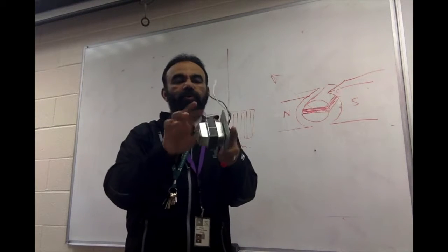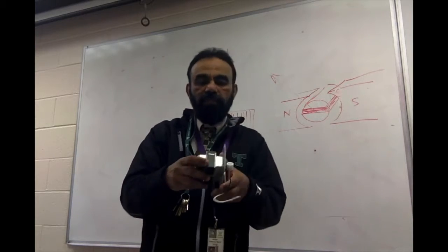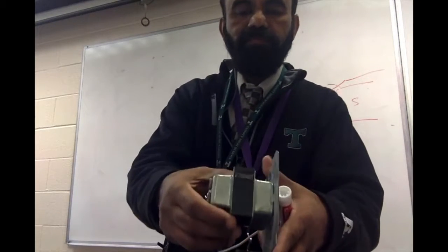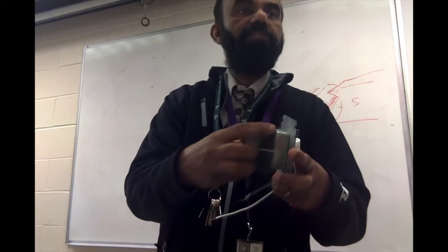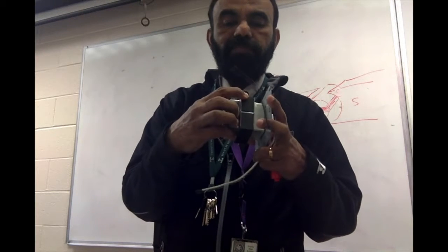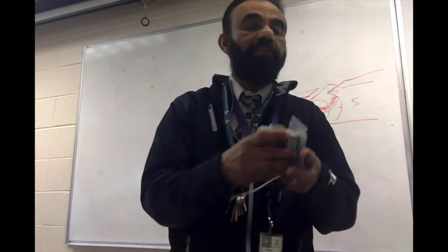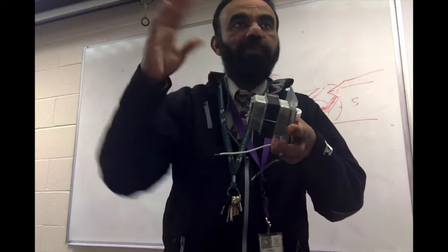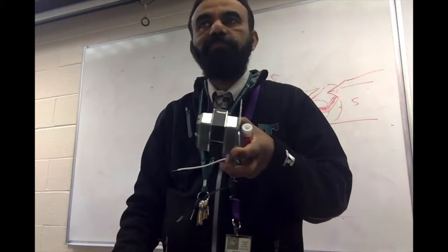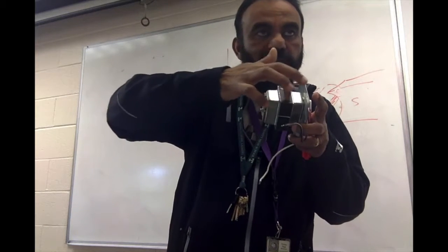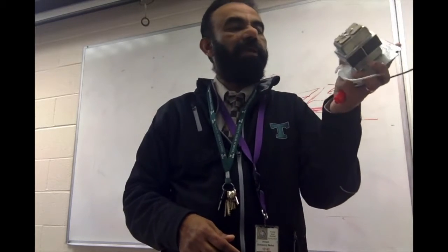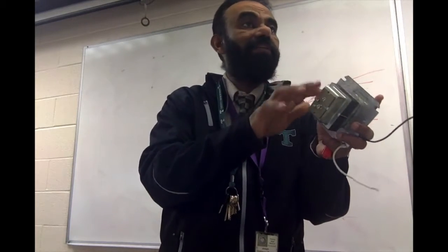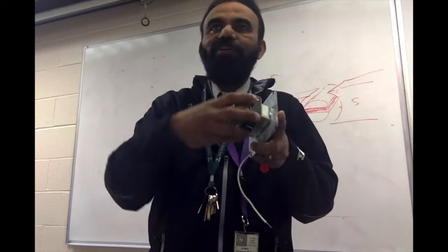So in a transformer core, these are laminations. You can see all these sheets are separated. At the same time, they're put together with a little bit of varnish in between. And therefore, electrically, there is no contact, but magnetically, there is full contact. Okay? So it prevents the circulatory currents, the eddy currents. And thereby the benefit is there is hardly any loss here. So when I use a transformer, this will not get heated up.